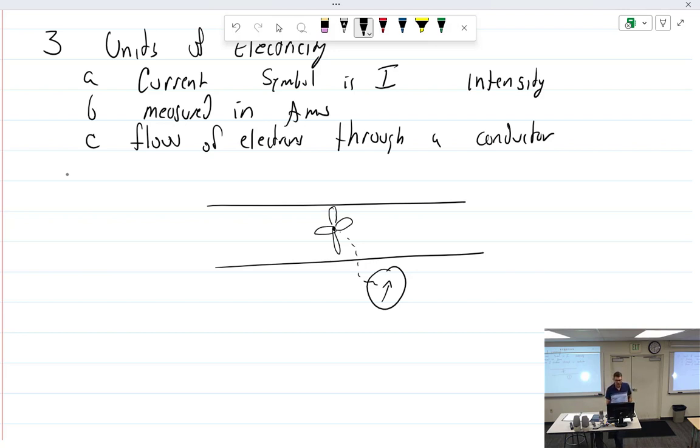If I were to make a parallel little pipe coming out of here and water bypassed it, would my flow be correct? No, it would not. So it can't be a parallel circuit. We have to measure flow. Flow is measured in series. All right, so amps are measured in series.